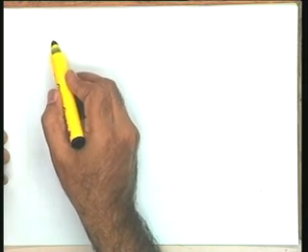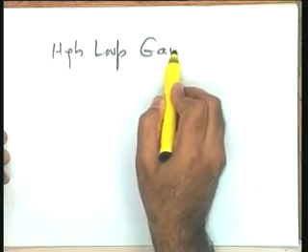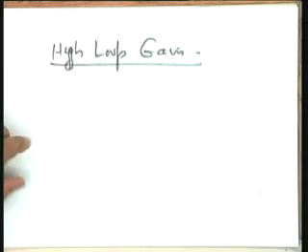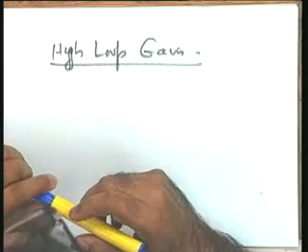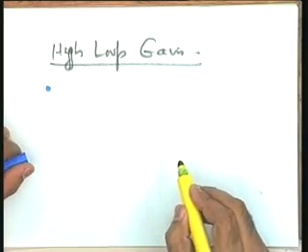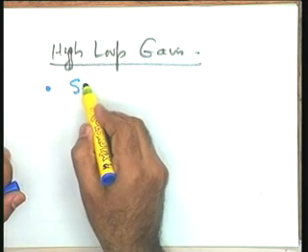I will really like to conclude this with certain summary points coming from you. We have seen all through that high loop gain is one of the design tools available with us. Maybe by high loop gain we are going to take care of many of the design requirements. Let us now list one by one what the high loop gain can do. Can it satisfy all the requirements, or can it create problems for us? High loop gain, as you have seen, makes sensitivity reduction possible.